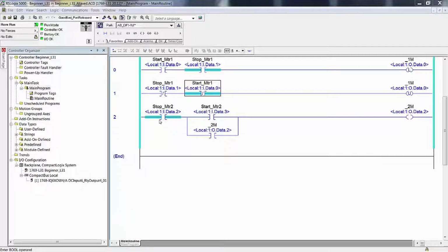Fail open is fail safe. Now because we're using toggle switches, we can toggle those switches on, the ones we're using for the stop inputs, and just consider that a normally closed button, because right now it's closed. It's at rest in the closed position. Keep it in mind that it's a toggle switch, so it has two at-rest positions, open and closed.